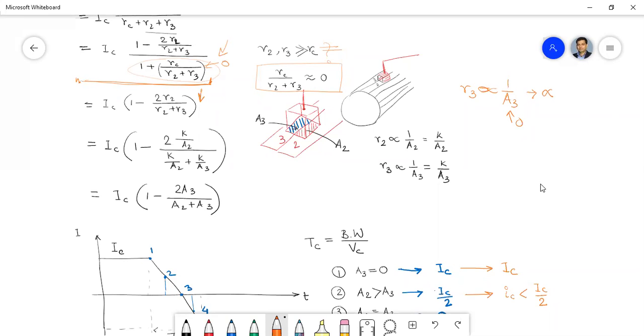That way also you can think, just physically, about the current. Only the current is flowing through the commutator segment 2, and that current is carrying the whole current. There is no branching at all, isn't it?